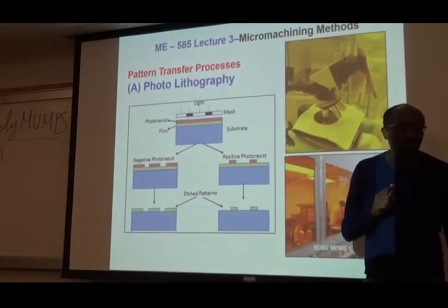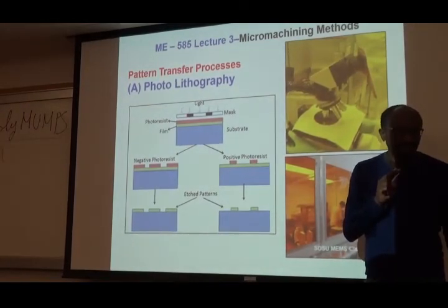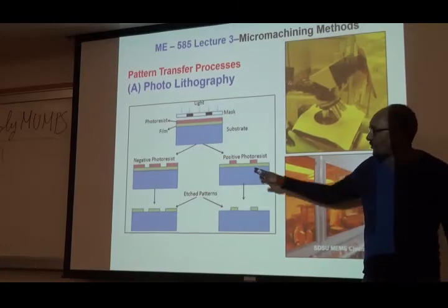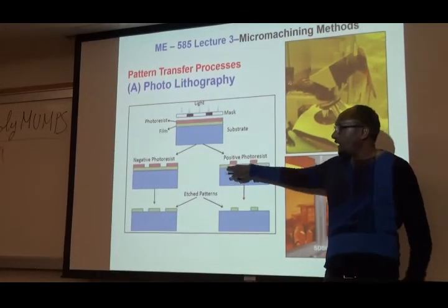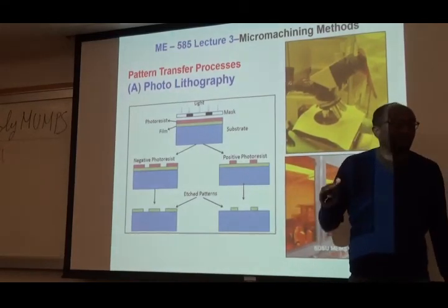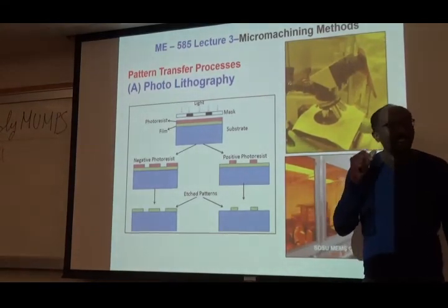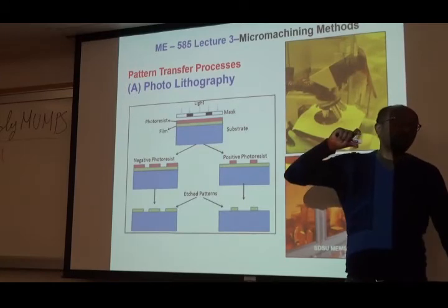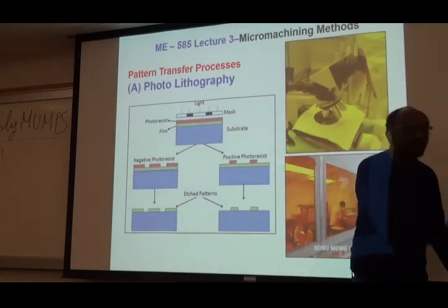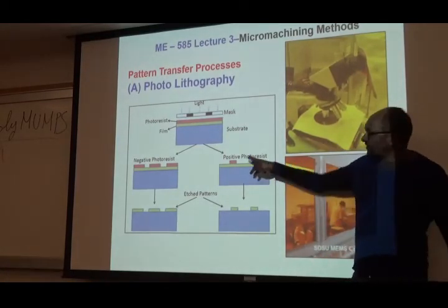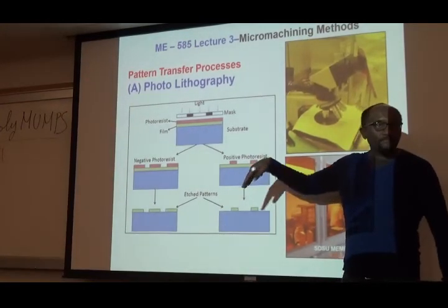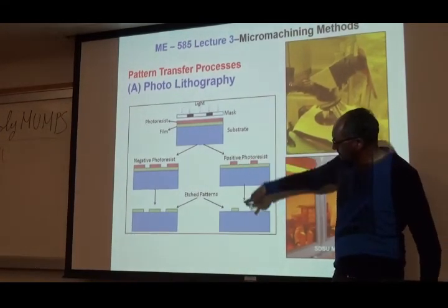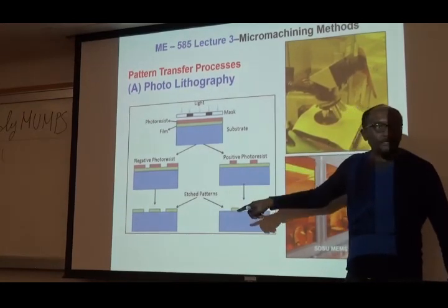In fact, the way I should have explained it, let me give it one more shot. The way I explained it, I said, okay, we pattern in such a way that this allows me to do a deposition, right? Selective deposition. That's number one. The other one is that it allows me to also do a selective removal. Now, in this particular case, in this cartoon, this guy's protected, I come in, and I'm going to etch away this part, but that guy is protected.